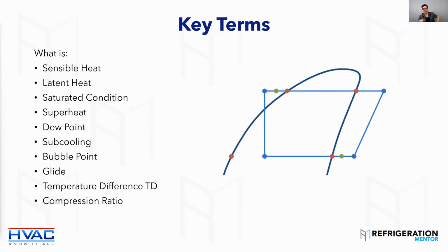When you have high compression ratio, what does that cause? That's a good question. High temps, hard work on your compressor. Yeah, heat, high temps, more work on that compressor. You're pushing it hard. And okay, here's another good one. Is it worse to have high discharge for compression ratio or a drop in suction pressure? So an increase in your condensing pressure or temperature, or a drop in your suction pressure or temperature?